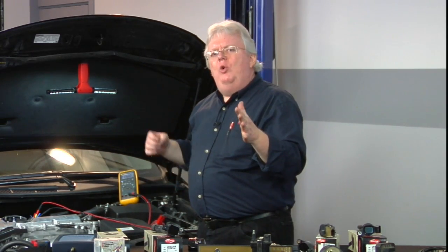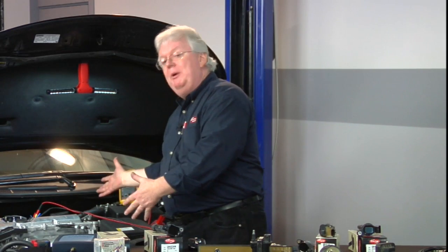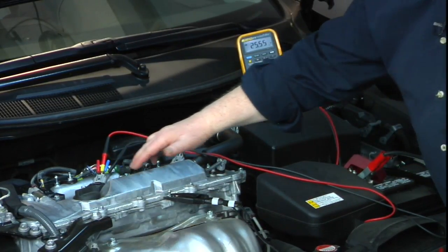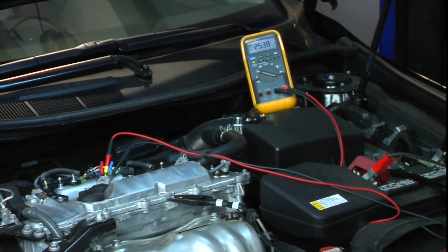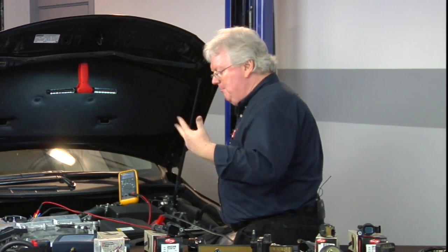So that's telling you you've got a signal. So that's telling you the wiring is good between the PCM and this coil. And we have a signal that the coil is putting out, or at least 3 of the 4, or 2 of the 4, whatever, but there is a coil putting that signal out, probably 4 of them. And we also saw on the blue connection, that was my trigger to make that particular number 2 coil power up, saturate, turn on, turn off, make spark. That's working too. Let's go ahead and shut it off.